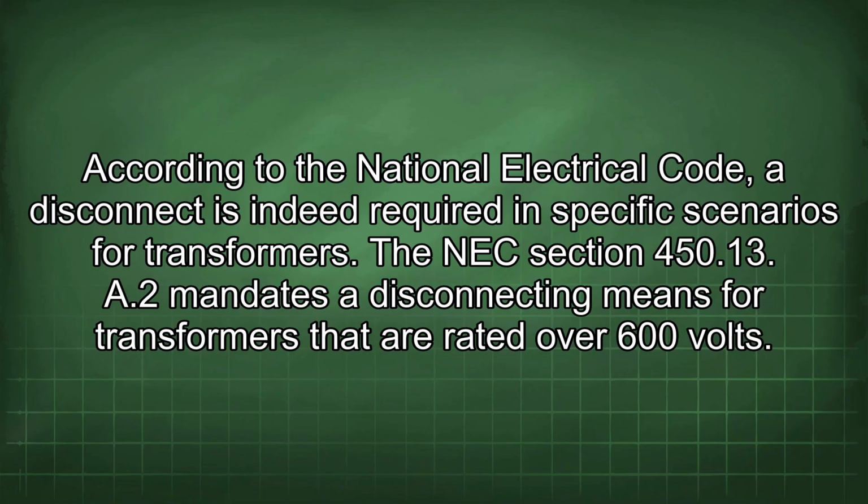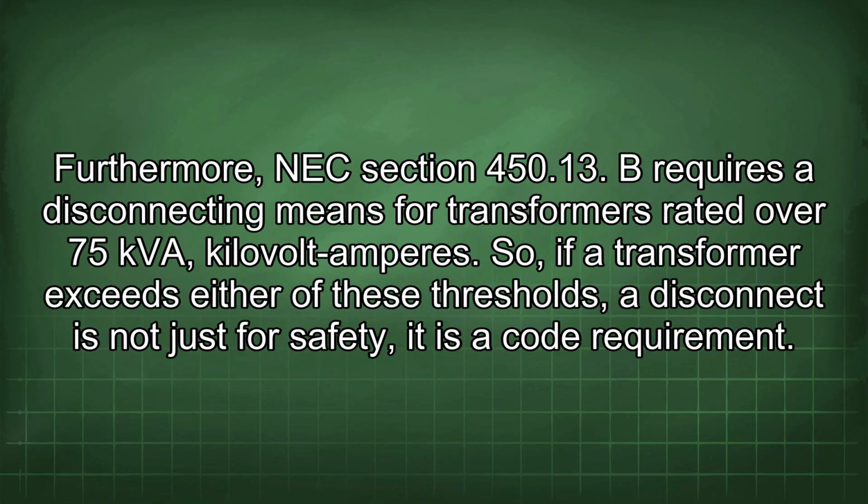According to the National Electrical Code, a disconnect is indeed required in specific scenarios for transformers. NEC Section 450.13(A)(2) mandates a disconnecting means for transformers that are rated over 600 volts. Furthermore, NEC Section 450.13(B) requires a disconnecting means for transformers rated over 75 kVA, kilovolt amperes. So, if a transformer exceeds either of these thresholds, a disconnect is not just for safety, it is a code